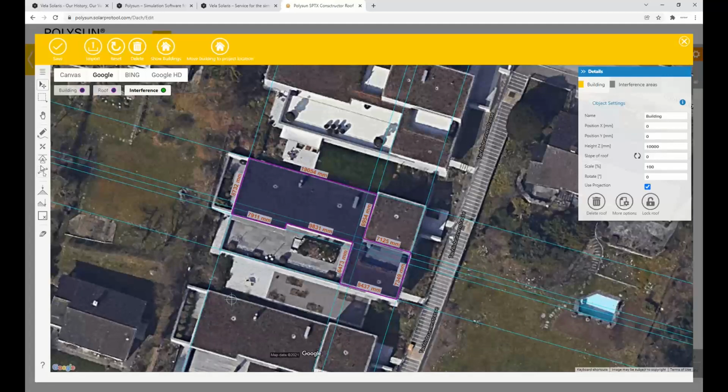And also at this step, it's important to already set the direction of the modules. Of course, per default, the modules are aligned facing south or completely east-west if you use the east-west setup. And to have the south set, to have it facing alongside the edge of the building, you need to use this A tool, which is, I think, German for something like orientation. So let's just put this facing at this edge here so it points inwards to the building, like that.